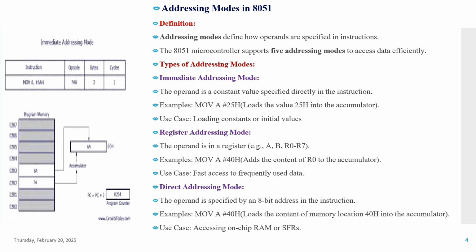Is the addressing mode of 8051. This is a very important topic in your syllabus. 8051, what is the addressing mode? The operand is a constant value specified directly in the instruction. And what is the example? MOV A, #25H, that is load the value 25H into the accumulator. A means accumulator. And it also loads constants or initial values directly into the registers.